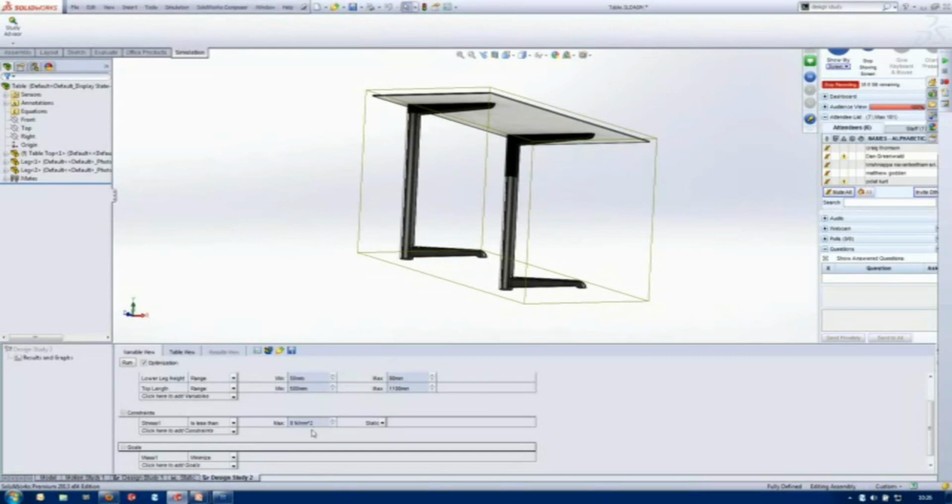stress in this model would be, I've realized I've not filled in that box. There we go. The easiest way to reduce the stress obviously would make these much bulkier. And potentially much longer as well, so that stress is added over a larger area. But obviously that's going to add more weight. Now, in this particular situation, I want to reduce the weight, and by reducing the weight, it's going to be cheaper to make theoretically.